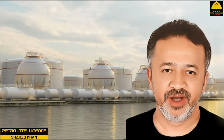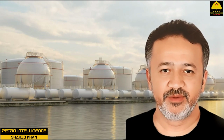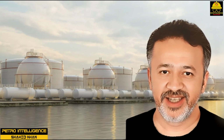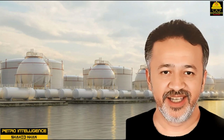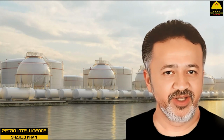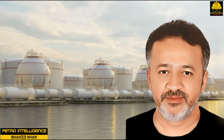Magnetic particle inspection is used to detect surface or near-surface flaws in equipment that can be magnetized. A magnetic field is induced, and an iron powder is dusted on the piece to be inspected. The iron powder adheres to the piece at any discontinuity in the magnetic field, thus outlining such defects as cracks, porosity, and inclusions, which are embedded foreign material.